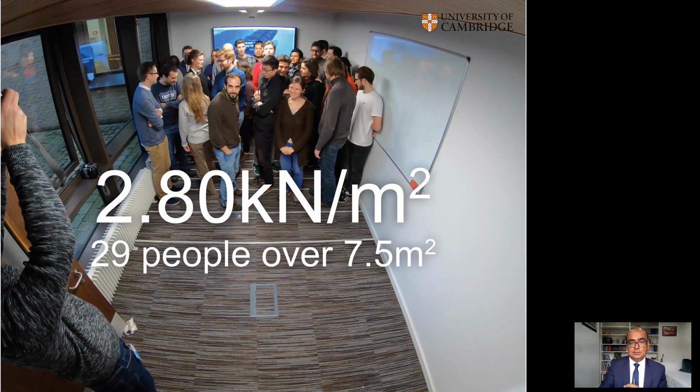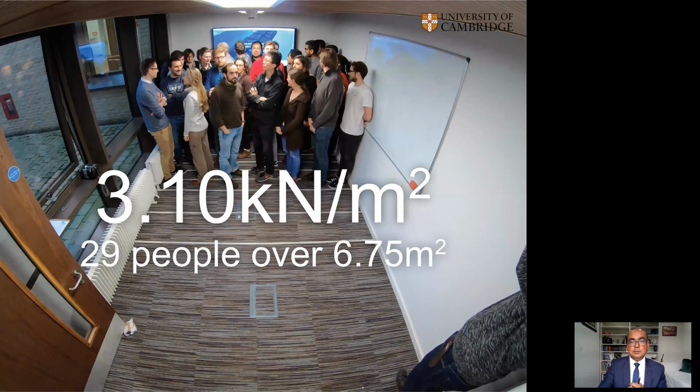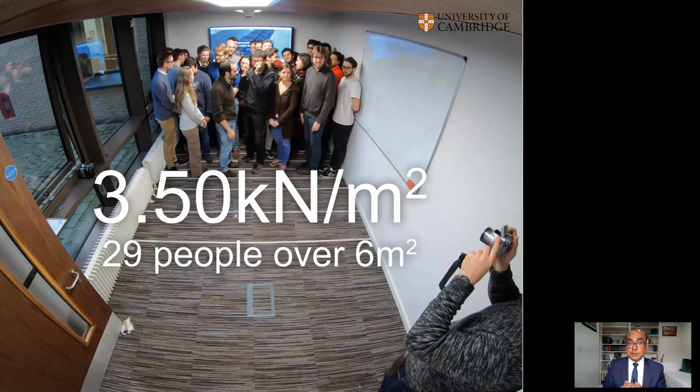People are getting cramped now. Then 3.1 kilonewton per meter square, 29 people over 6.75 meter square. 3.5 kilonewton per meter square, where 29 people are standing over 6 meters square of area. They are even more cramped. It looks like the London Tube here.